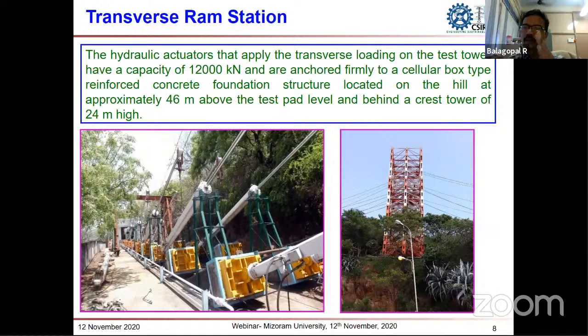If we apply load at one point and stop, then go to the bottom point, then in a winch application there will be a release of load due to the application of load at the other point. But in our hydraulic closed-loop servo control system, it takes care of this until all the desired loads are applied. If 10 kilonewtons has to be applied at all 8 points, it continuously gives feedback to the drive actuator, so that the desired load is applied at all the loading points.